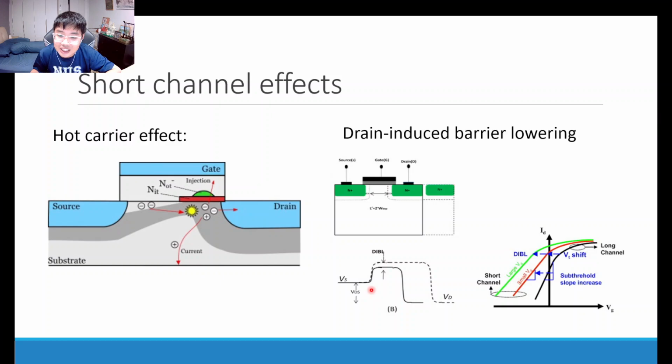When the transistor is in the off state, basically due to the band diagram of the semiconductors, which I forgot to show here, but I guess we probably don't have to go into that depth, you can draw the band structure and show that when the Fermi levels align at equilibrium, in the absence of a gate voltage, there will be an energy barrier throughout the whole channel that prevents basically source to drain current flow when the transistor is off.